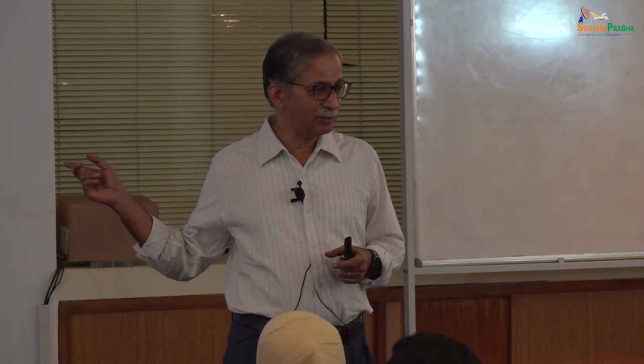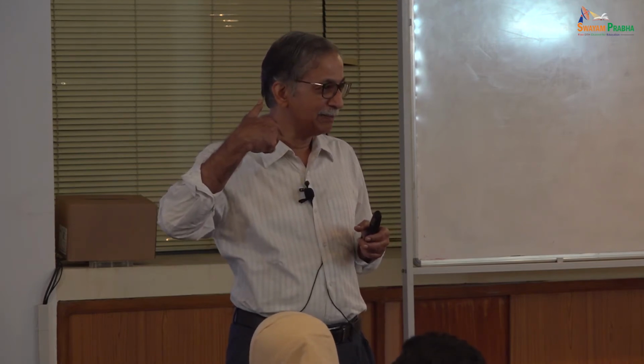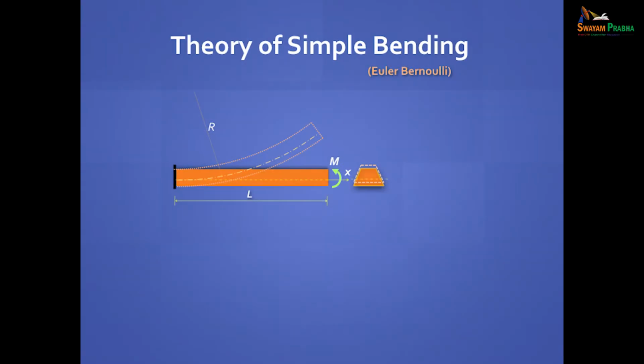You can, but you have to be careful. It's not the same as this because there is going to be some transverse bending. It's not just longitudinal bending. Do you understand what I'm saying? If you don't have transverse bending, this will just move vertically up or down. So that's one assumption we are making.